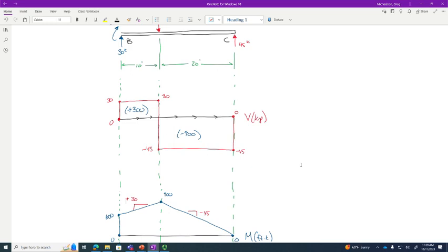The moment changes, right? With a truss member, it doesn't matter where I cut the section, I'm going to get the same internal response. For a beam, though, it does, because by the nature of a shear and moment diagram, the internal response changes depending upon where you look, right?